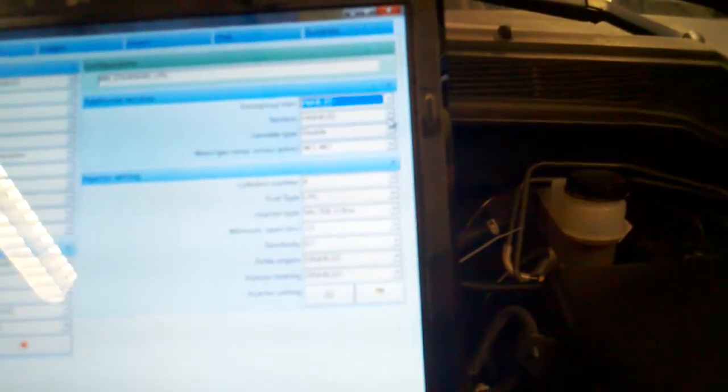Services. This one is our secondary lock-off. So you saw how we had the 2 extra lock-off wires that would normally go to the tank. It's described really well in the book. I've never needed to use it, but you can actually make those wires do other functions. If you have another solenoid or any 12-volt source that you want to control, you can do it in here to do different things with that. So we leave it disabled since we're using it for its intended purpose.